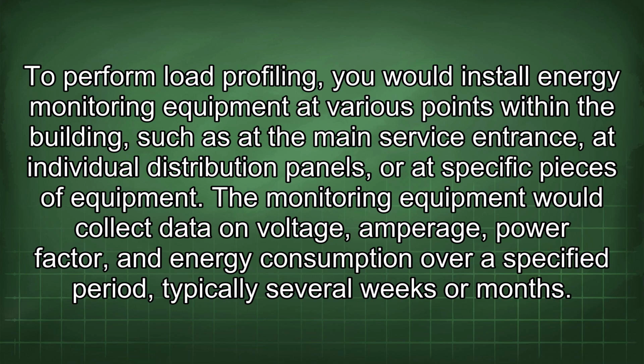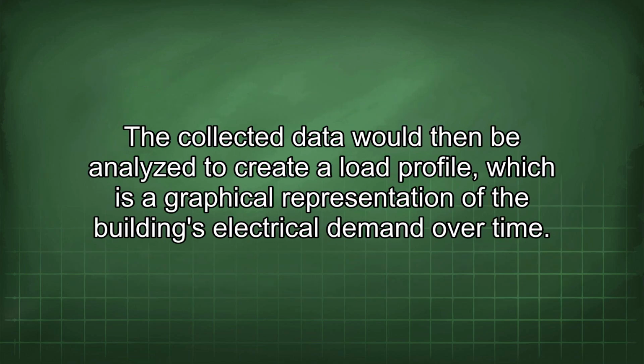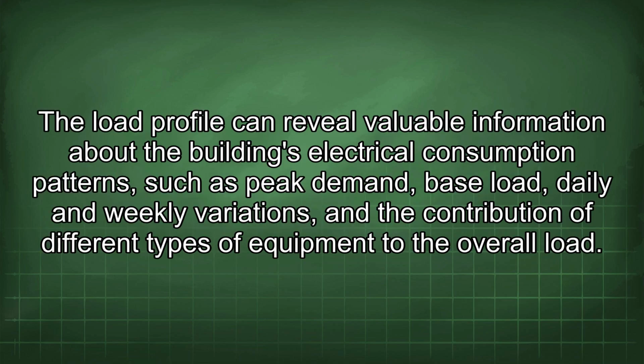The monitoring equipment would collect data on voltage, amperage, power factor, and energy consumption over a specified period, typically several weeks or months. The collected data would then be analyzed to create a load profile, which is a graphical representation of the building's electrical demand over time. The load profile can reveal valuable information about the building's electrical consumption patterns, such as peak demand, base load, daily and weekly variations, and the contribution of different types of equipment to the overall load.